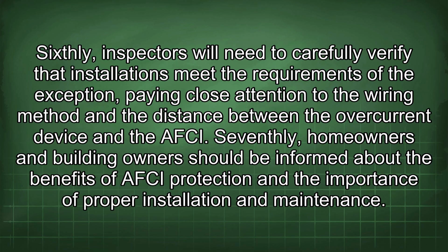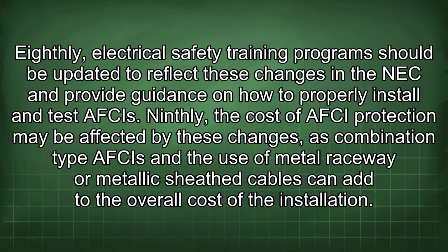Seventhly, homeowners and building owners should be informed about the benefits of AFCI protection and the importance of proper installation and maintenance. Eighthly, electrical safety training programs should be updated to reflect these changes in the NEC and provide guidance on how to properly install and test AFCIs. Ninthly, the cost of AFCI protection may be affected by these changes, as combination type AFCIs and the use of metal raceway or metallic sheath cables can add to the overall cost of the installation.